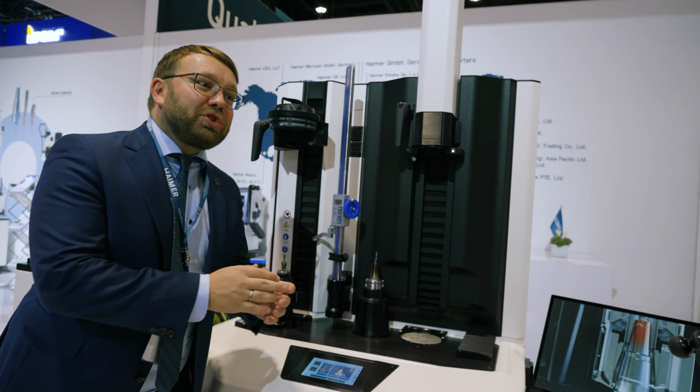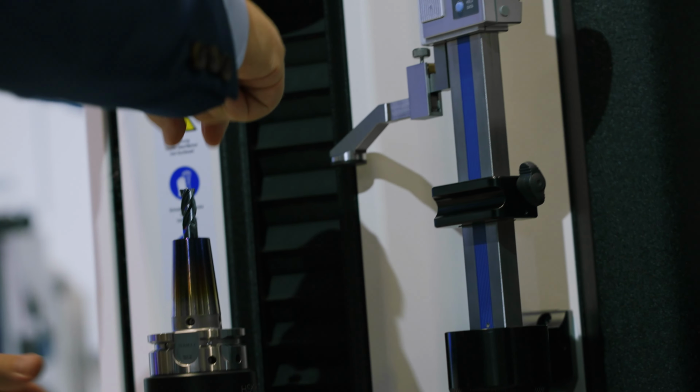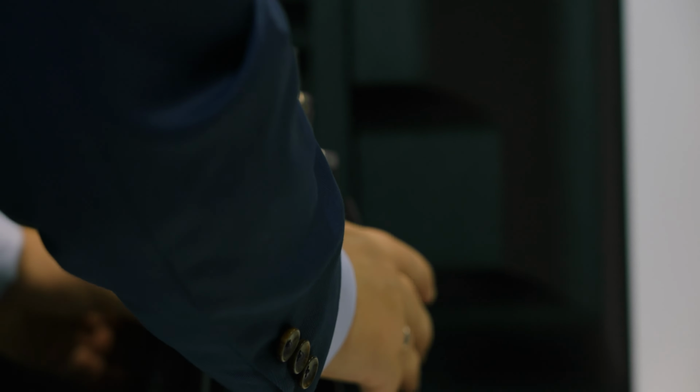That's a Shrinkfit, we call it. In this case, it's ideal for lathe or driven tools. Then we move it down. It sees it's hot. It's moving on, and that's a kind of vortex cooling. Cooling time has been much more reduced for this kind of puncture independent cooling. So while the one is cooling down, I shrink the next one. It moves to the right position. See, it's even so quick, I cannot change the tool at the same time because it's already cooled down. So I put it in, take it out. So you can work multitasking and cool it down.